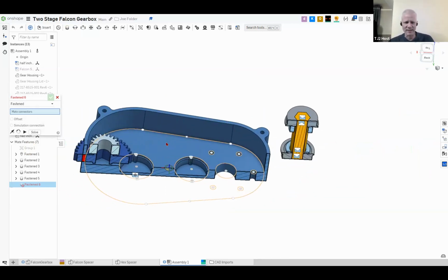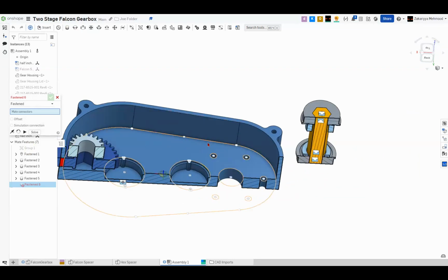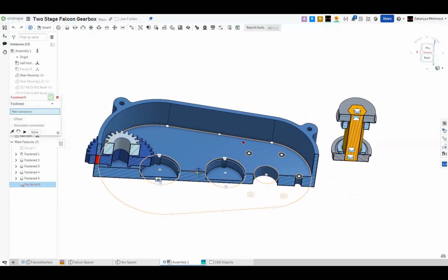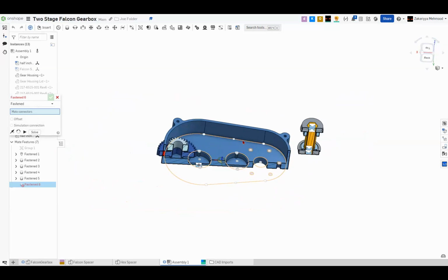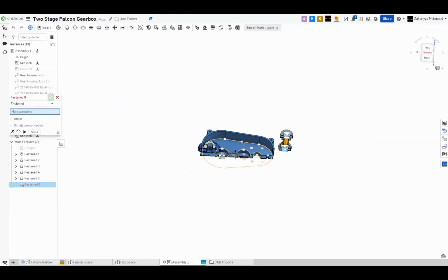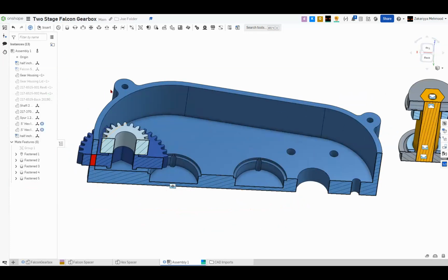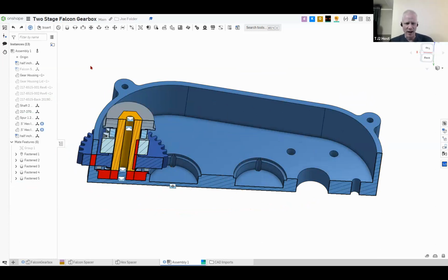Okay, we can mate them, I guess. It's not that hard. You have to make sure you're pressing Control as well as Z. Yeah, I'm pressing Control and Z. I'm pressing them both. Oh, you have to click out of the fasten mate first. That's it. Okay, now hit Control Z. Yes, yes. Okay, so keep going. There we go. Now fine, perfect.